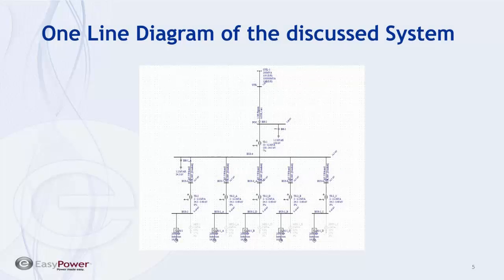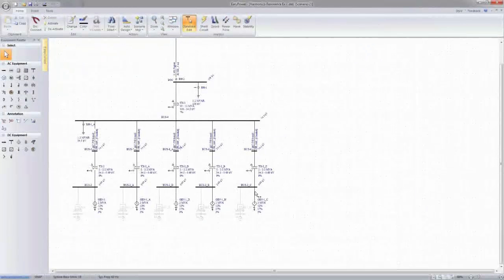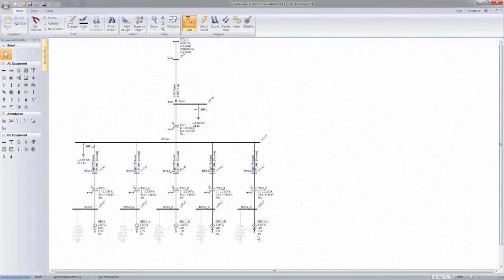Now, this is a screenshot of the system that I put together before. I can just put it back here because I'm using the same system here, except for the fact that you would see that now there are these motors with the rectifiers, in fact harmonic sources being added here, which means that this part of the system you had it for your power flow calculation, and for the harmonic calculation you will have these new sources being added to the buses which inject harmonics into the system.